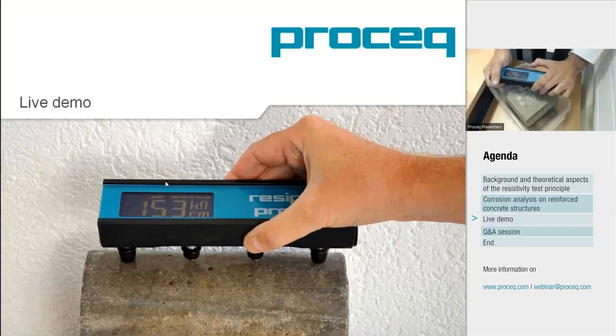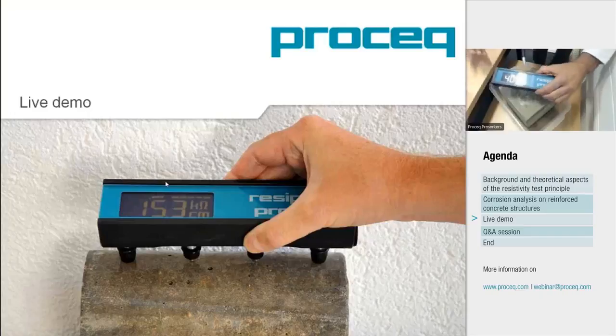Let me freeze this measurement for a minute. Here we see our actual value of resistivity, and on the top of the monitor we have an indication of the current that flows between the outer probes. We want to make sure that contacts are good. So here we have an indication of the top of the global scale of the current, which in this case is 200 microampere, and it could be a lower range for lower resistivity.